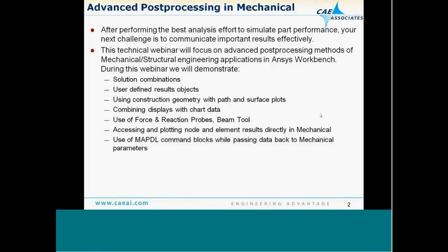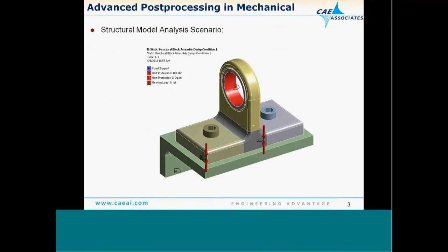Also, if some of you have some MAPDL commands that you use for post-processing, we'll show you how to use those within the Workbench environment and access and pass back and forth some key information data. The particular model I'll be covering is a structural example. This is a pillow block tied down with a couple bolts with some bolt preload and two various load cases. One, we have a bearing load inside this bearing race, and then also a secondary load where we apply a pressure on this face.